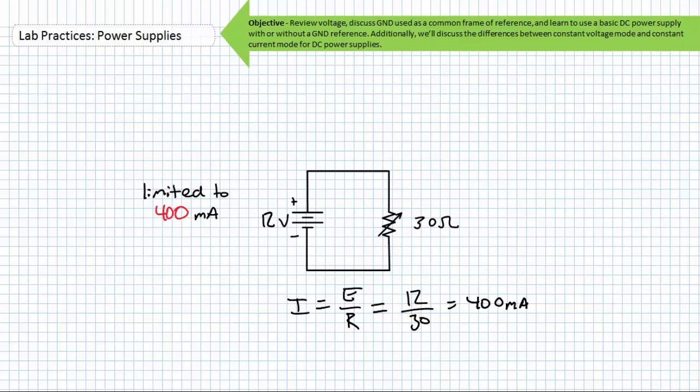Having discussed this, ordinarily power supplies are run in constant voltage mode, and constant current mode is typically used only as a safety backup. In the event of an errant short, a power supply simply enters constant current mode to keep the short from becoming a toaster. Additionally, this independently adjustable current knob could be used as a fail-safe limit for sensitive electronics components that need to be protected against high current values. The current limit is simply adjusted at or below this maximum value, and the power supply will not exceed it.